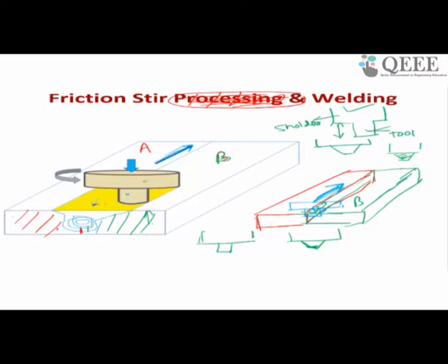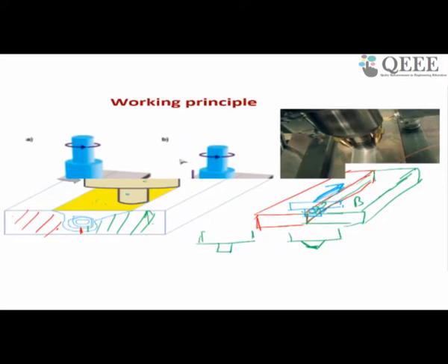However, in friction stir welding, because of severe plastic deformation, grain refinement also occurs at the interface, at the joining region. Since the grains are smaller than the base material, the strength inside the friction stir zone is very high as compared to the base material. That's why the joint strength in friction stir welding is very high. That's why a lot of research work is going on in this process, and this is the newest joining process till now.